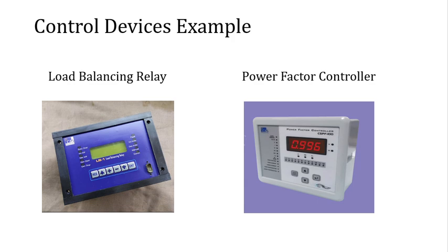Another important point is you should know what parameter of the engine needs to be controlled to bring about this kVA sharing control. And yes, another point, you should know how to control that set of parameters with your embedded device. With a load balancing relay, we achieve this function automatically and continuously.